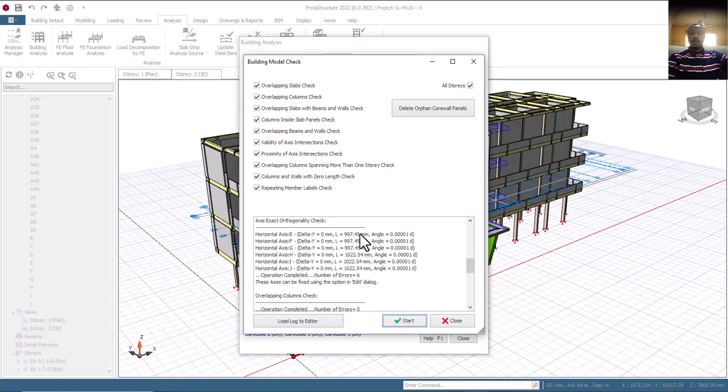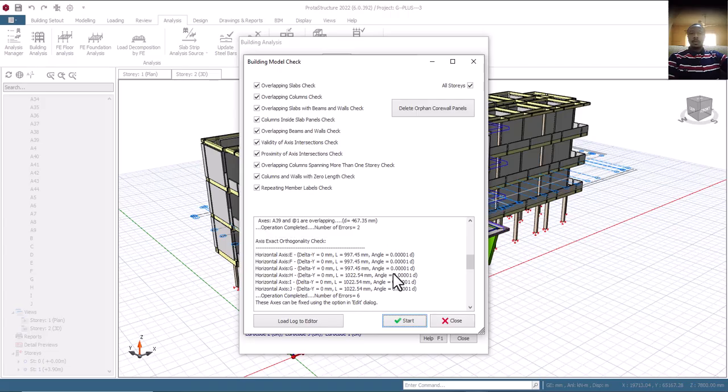Why we are having this is because the axes we are talking about are not up to the required length. Is that okay? You can see from this axis to the last one is very long, isn't it? So we have short axes that are not up to the required length. In this kind of error, you can see there are 6. It can be ignored. When you have something like this, you can ignore them. Is that okay? Because you purposely make use of them. Or the option you have is to go and increase the length by using stretch axis. Is that okay? So that is that.